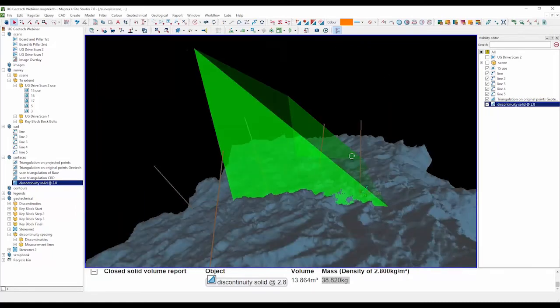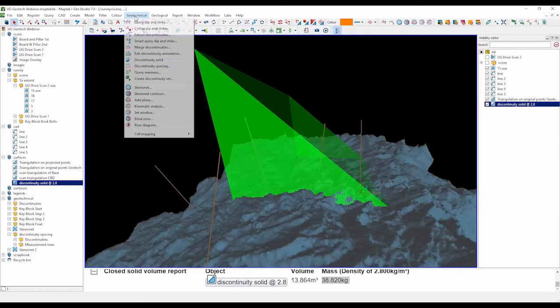Right, so again, with regards to the Q system, that rock bolt analysis, guys can do some reconciliation of the rock bolt distribution and extrapolation. Guys can also do this for rock anchors as well. And according to your mine legislation, you can also check your joint spacing either in advance or going sideways. So in addition to that, we also have the waviness tool.